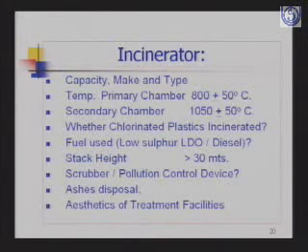If you are talking of the double chamber incinerator, we can see what is the capacity, make and type of the incinerator. The temperature in the primary chamber should be 800 plus or minus 50 degrees Celsius. In the secondary chamber it should be 1050 plus or minus 50 degrees Celsius. We should keep in mind whether we are incinerating chlorinated plastic material, which we should not. The fuel used may be sulfur or diesel. Then stack height of the incinerator should be more than 30 meters. We should use a scrubber or pollution control device. Ash disposal should be kept in mind, and aesthetics of the treatment facility should always be kept.